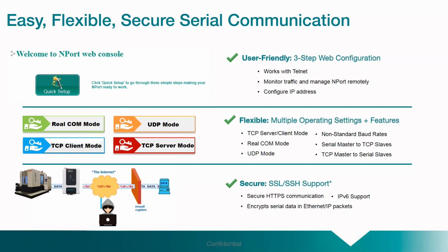Also, you have different operating modes and different features. So you have things like Real COM mode, which allows you to take that legacy device, bring it on board, and it doesn't know any better. It just thinks that it's talking to another serial port. But you have your application that you're able to install that virtual COM port, and now you're able to establish that communication, and you can get the readings, you can do the programming, troubleshooting, all that good stuff. Also, we handle non-standard baud rates, right? So that's a really big one, especially because we're talking about those industrial protocols.